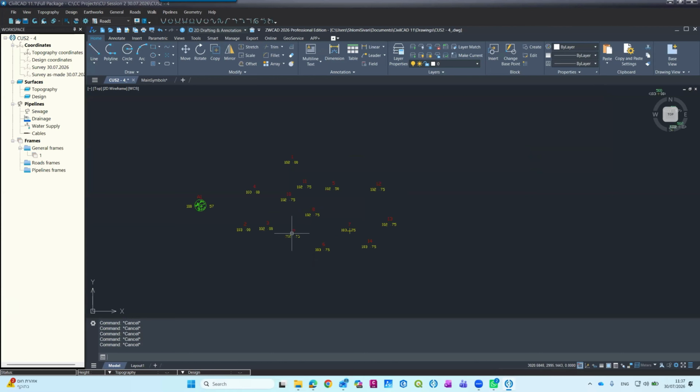By default, since this is the coordinates list, topography list, recall that I've used this one, automatically there is a predefined surface for it named topography. So topography is automatically assigned to topography coordinates, and design is automatically assigned to design coordinates. If I want to create another surface, I can create another surface, new surface. I'll call it new survey.